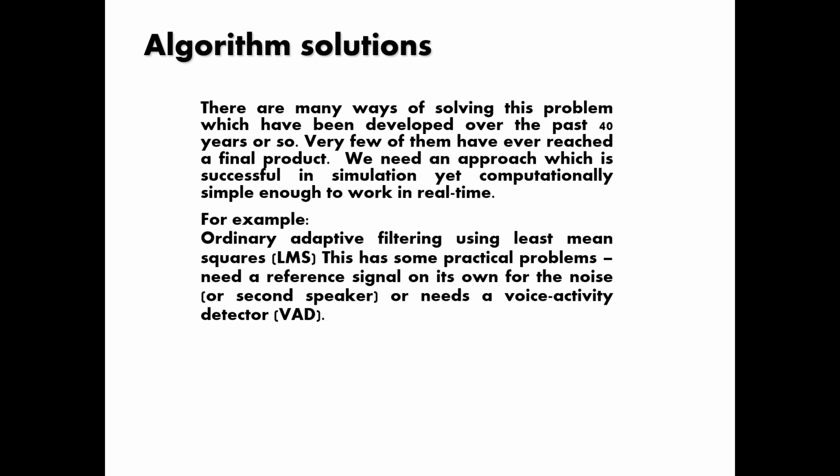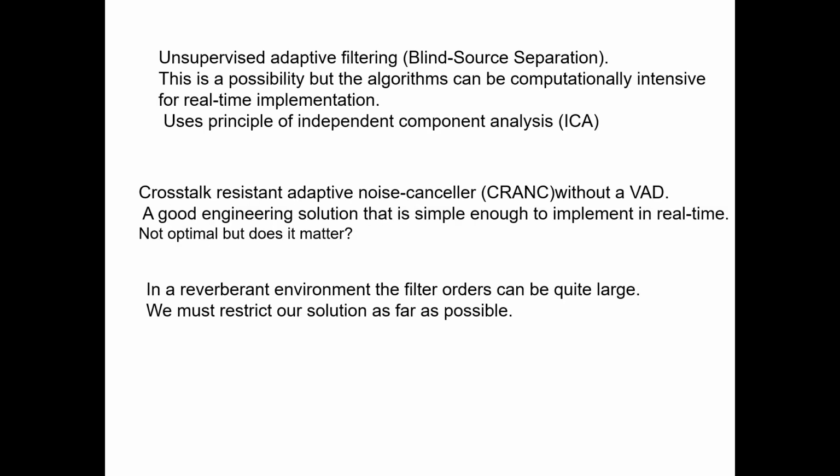Now you can do that sometimes in some applications, where it's just one speaker, and in between utterances the noise appears, or if the speaker pauses like this, then the noise is in the background and you can estimate the noise. So there's ways around that. You can use spectral subtraction, which was one of the earliest methods, and then least mean squares came out, and there's a whole load of applications on that. So this is a variation on that method, but the one I'm going to show you first isn't. It's a newer method.